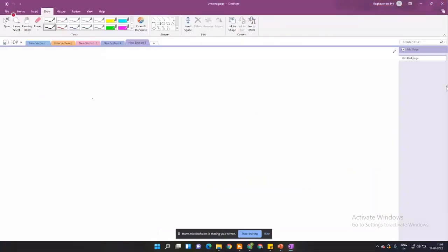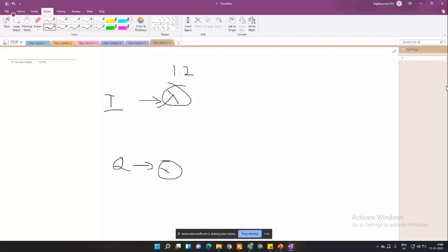I'll give you an example. Let's say my mixer is giving an I gain of 1.2 and my Q gain as 1. If I am an engineer tasked with getting rid of these IQ impairments, inside the IQ impairment block I firstly receive the I and the Q from my system.